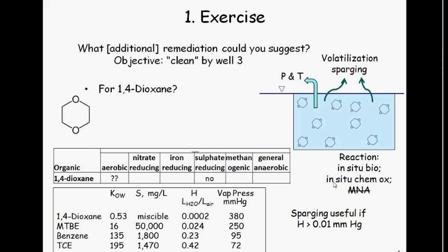1,4-dioxane. Again, MNA didn't work. What about pump and treat? Well, dioxane is miscible. It's very, very soluble, doesn't absorb at all. So pump and treat would probably work. Is it volatile enough? Compared to this very high solubility, no. The Henry's law constant is very small.